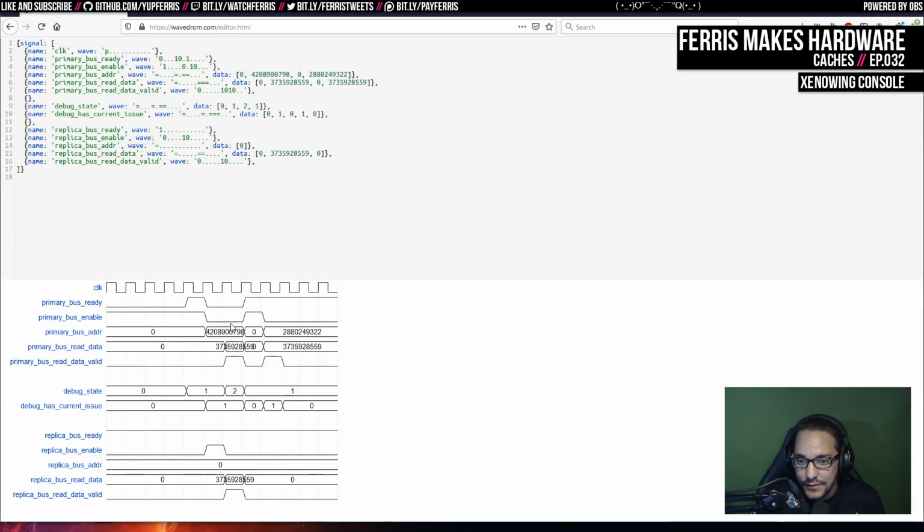If this is going to be a CPU cache, I might actually make this two-way associative. I'm not sure yet though. And right now this isn't that useful for the CPU because of the way that I have the memory hierarchy set up. It should actually help performance a little bit in the cases where it hits, but I need to do more testing before I actually hook it up.